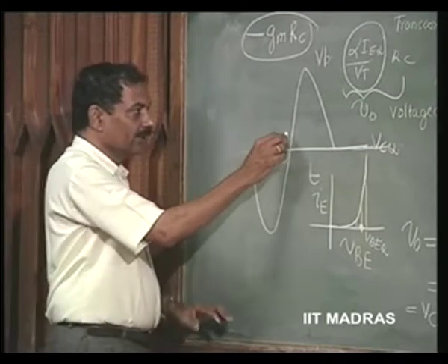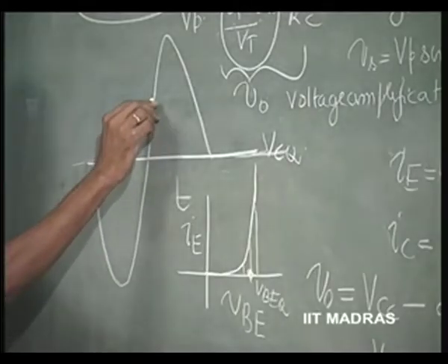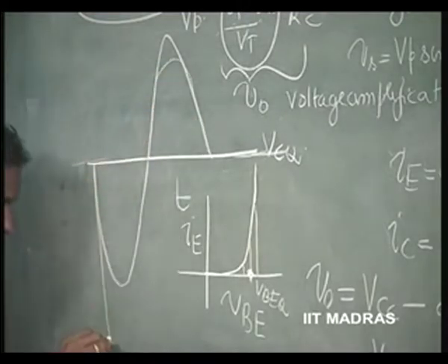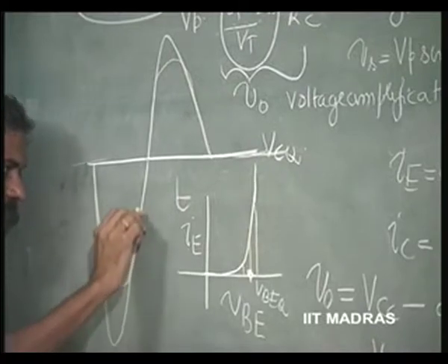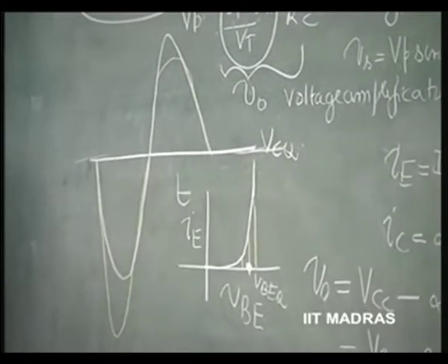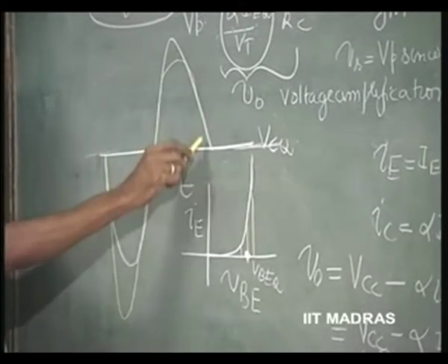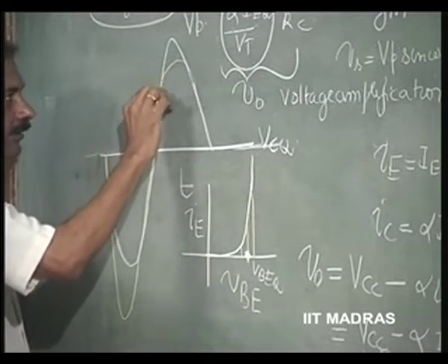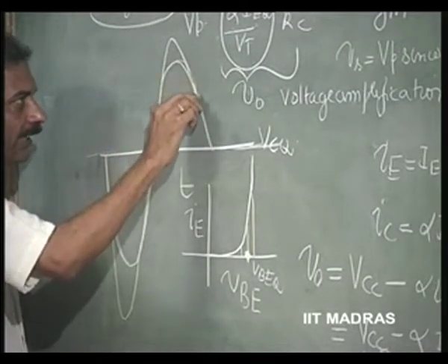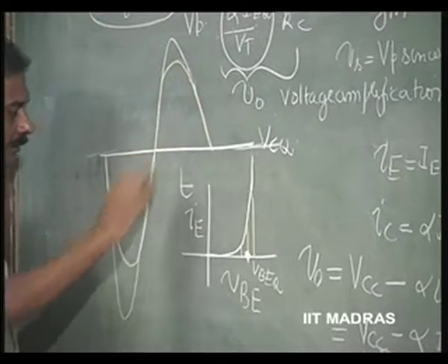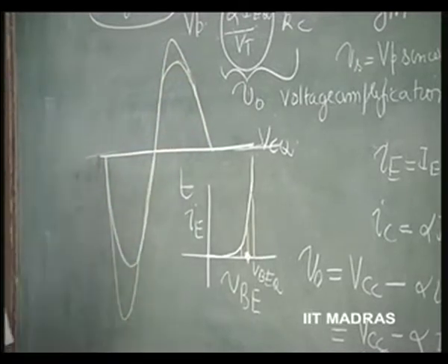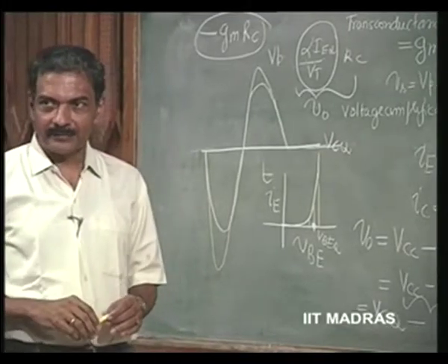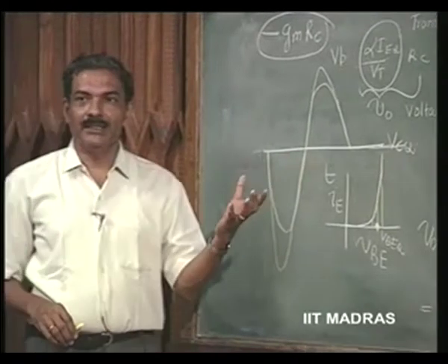So, this is going to become flatter, and this is going to become longer. This is what you expect under linear behavior. Because of the nonlinear behavior, this is going to become flatter and this is going to become longer. This is because of the exponent nonlinearity. This is exactly what you will see on your oscilloscope.